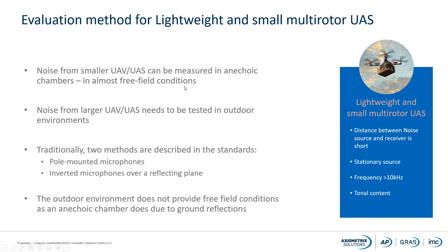So there is also another issue. You can say that, well, UAS, they are very small, and therefore you can test them in an anechoic chamber, which means that you can have almost free field conditions. That is possible for smaller drones and UAVs, but the problem is if you're having a little bit larger UAV or UAS, they need to be tested in outdoor environments.